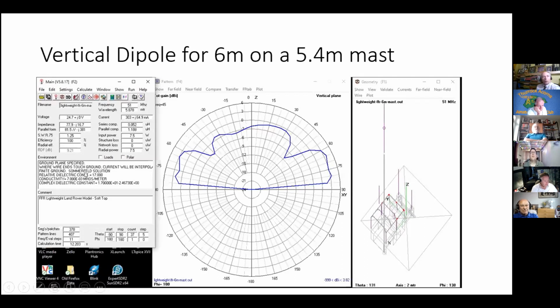I've set it up with what they call a fertile land ground, which there is a table of different ground conductivities and ground dielectric constants for everything basically from salt water to sand. And that makes a huge difference, particularly to fields between the antenna and earth and real ground. And you can also model a perfect metal plate ground if you really want to.